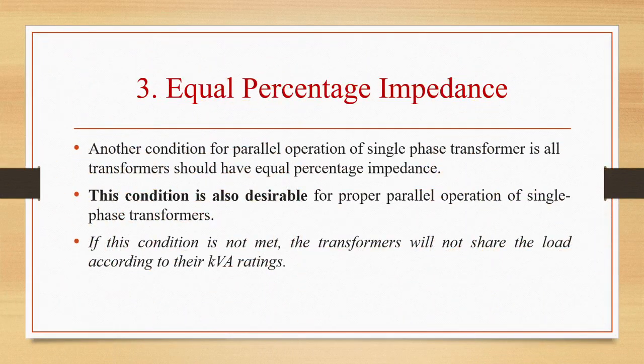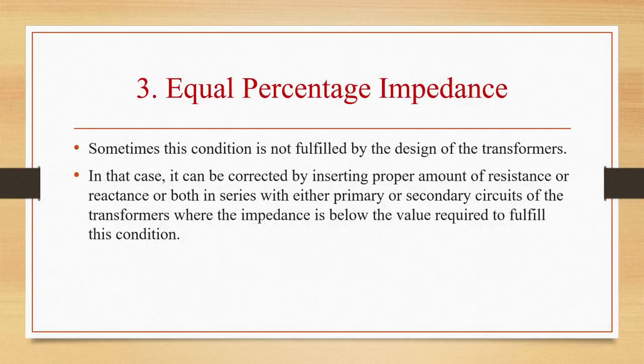Next, another condition for parallel operation of single phase transformers is that all transformers should have equal percentage impedance. This condition is also desirable for proper parallel operation of single phase transformers. If this condition is not met, transformers will not share the load according to their kVA ratings.